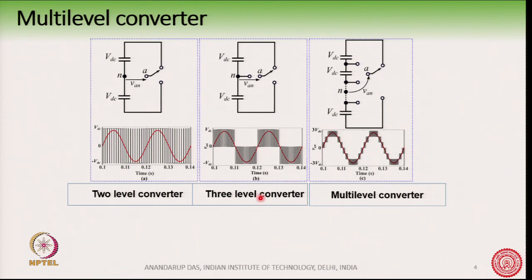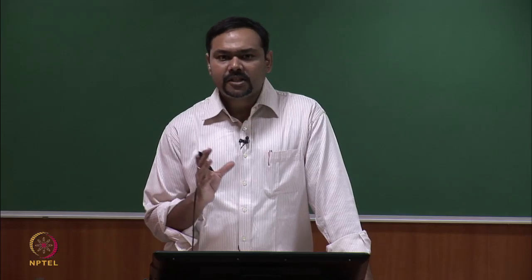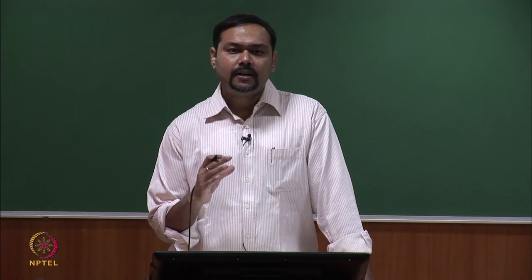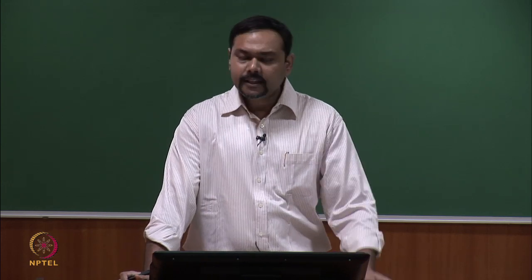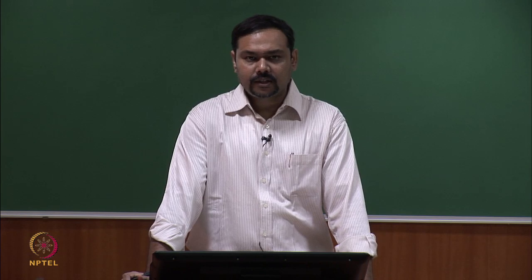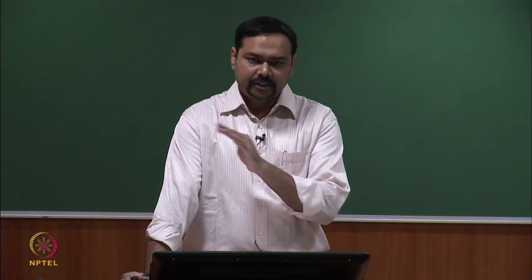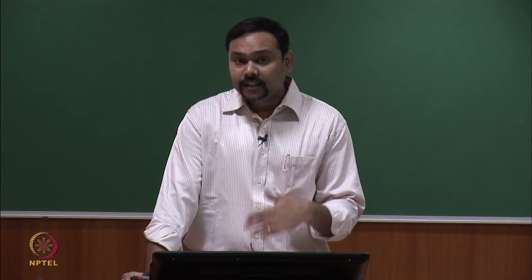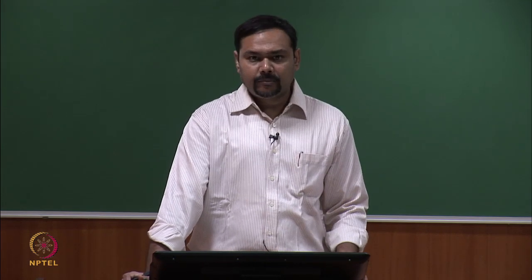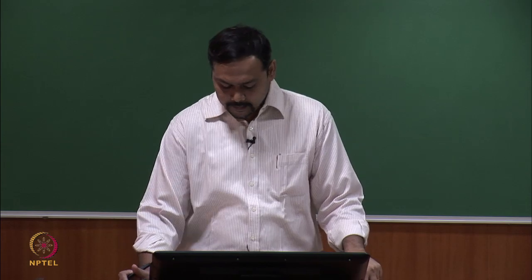Now, let us go to another converter which we call a multi-level converter. 3 level converter is also a multi-level converter, but 3 level is sometimes specifically reserved word. Anything more than 2 level is a multi-level converter, but usually we keep this 3 level word separate. So, anything more than 3 level we sometimes call a multi-level converter.